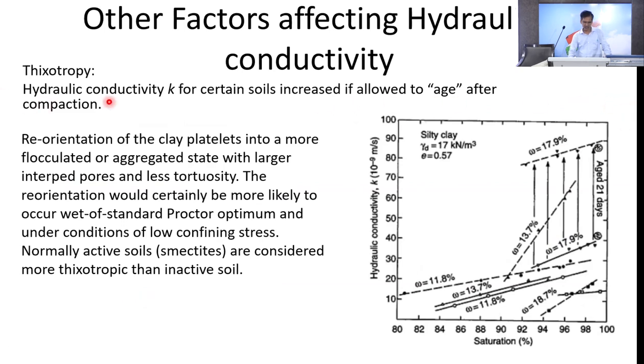This is called thixotropy, which we see in clay. You see, even after 21 days, the hydraulic conductivity reduced. It is the same thing: I only wait for 21 days, and it also reduces. That is another aspect of permeability. I am just trying to highlight the factors which may affect permeability.